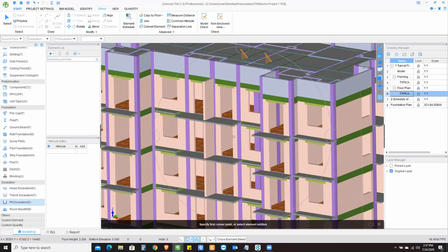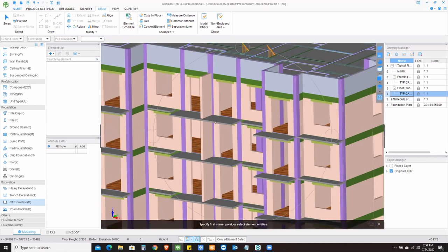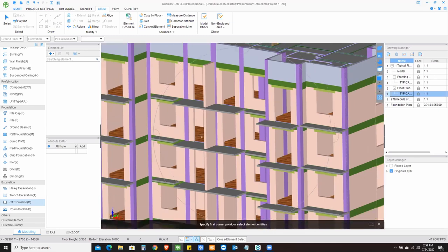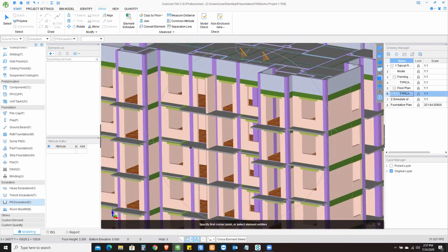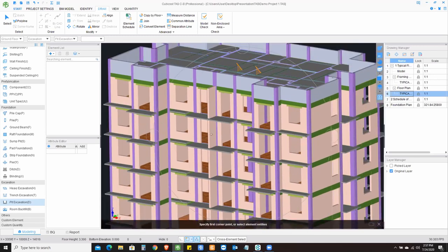So to conclude the modeling part, for the CAD and Excel user, and obviously we got a really good percentage of people who are using CAD and Excel, the software goes really handy. What I mean by that is that the software has got all the shortcut keys similar to AutoCAD. So EX for extend, TR for trim, L for line, all of these 2D lines you can draw, and you can do the 3D modeling using these shortcut keys, same as AutoCAD.